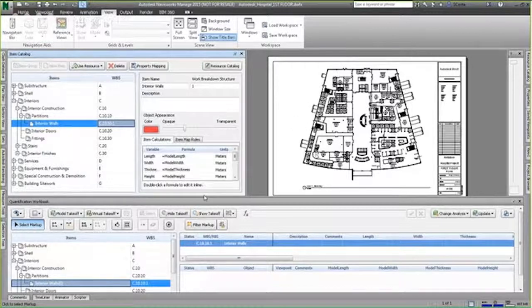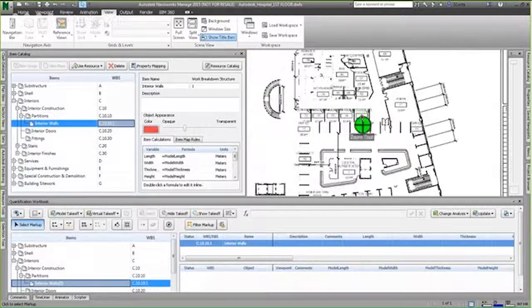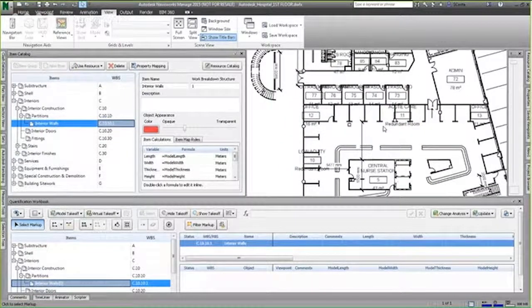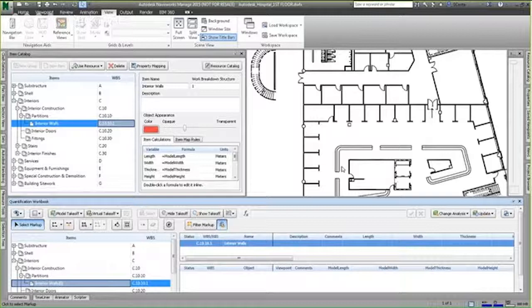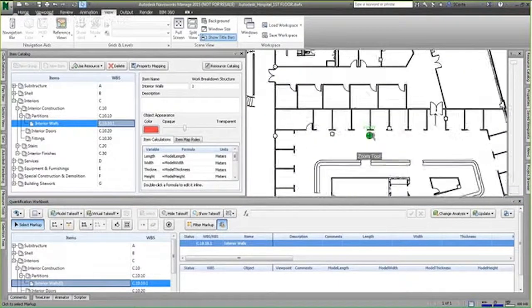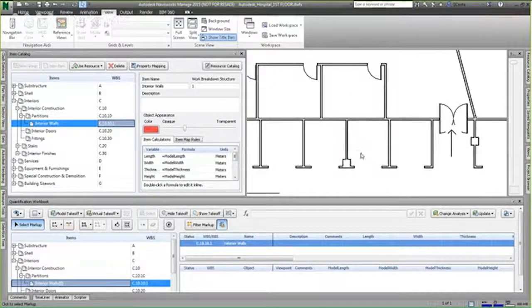With that, I can zoom into a particular area, it doesn't really matter where, and start analyzing what I want to take off. First thing I'll point out, if you ever notice this tool, is the ability to hide background and annotation. It queries the DWF file, in this case because it came from Revit, for certain types of annotated families. If I toggle that, you'll see that it turned off some of those room tags, section markers, and dimensions. So it really helps you, in one quick go, turn off a lot of the things that would clutter your worksheet, so that you can do some takeoffs.